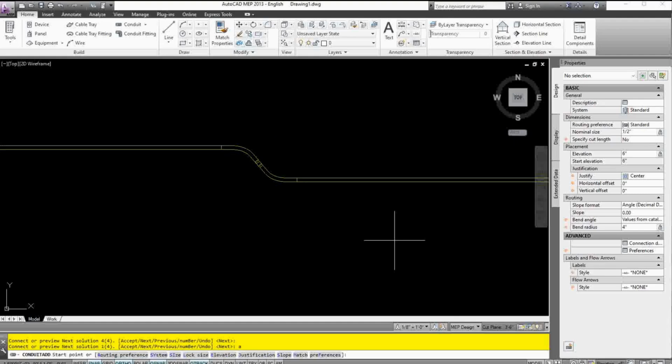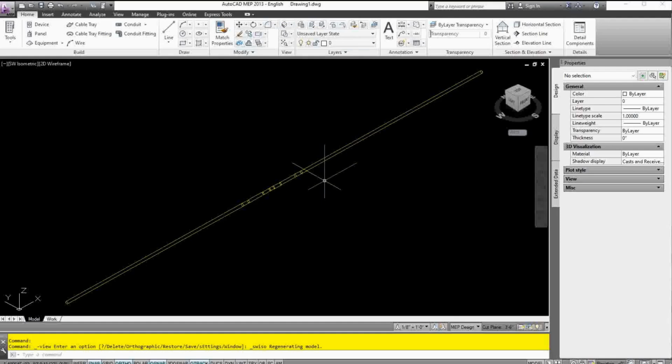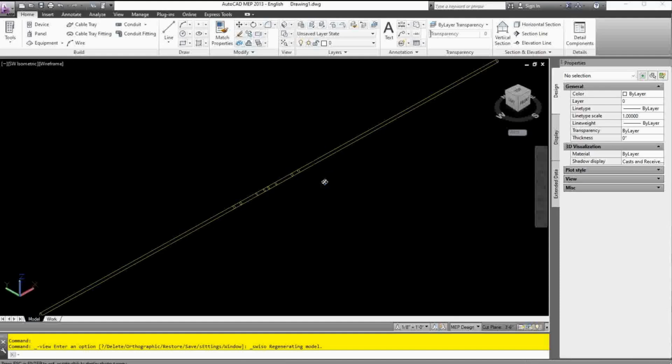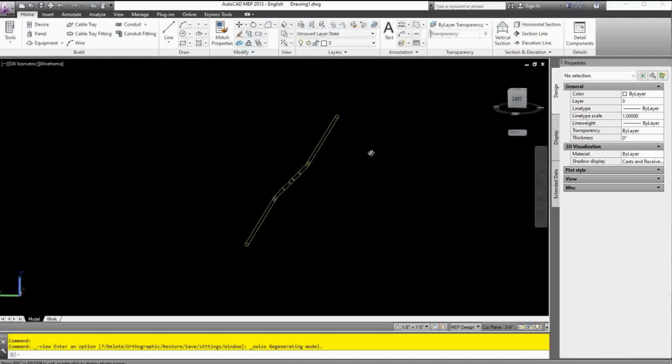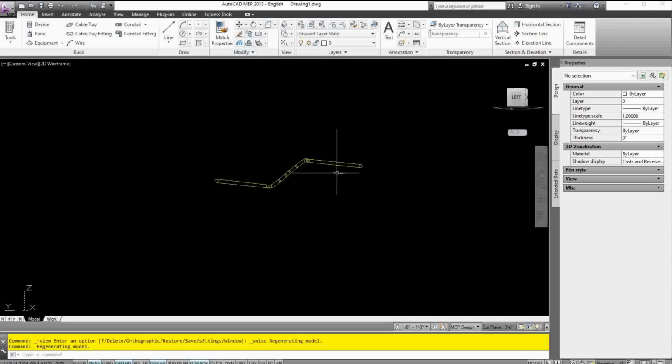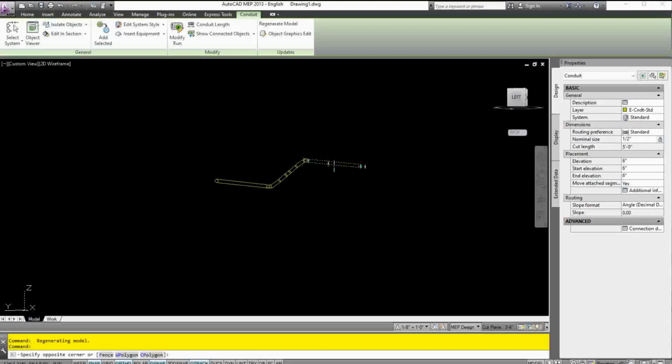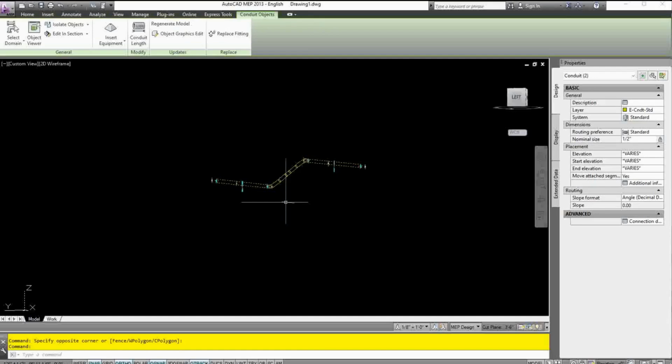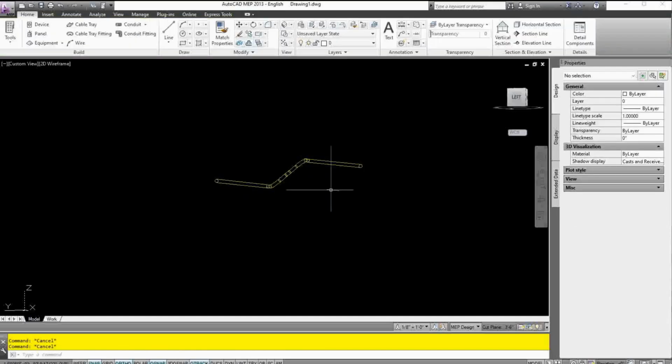Shazam, look at that. Hold down the shift key with your left pinky, on the left side of your keyboard. Press down on the wheel of your mouse and roll that pipe around until you see this view. Let's try to get it like this, and how about like that? We could talk about it. See, this pipe is higher than this pipe, right here. And that was our rolling offset.